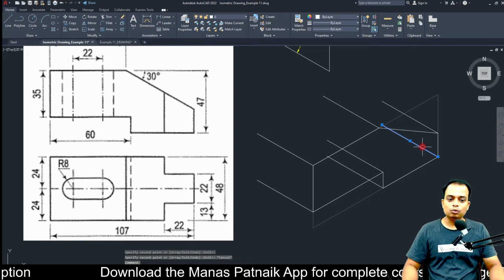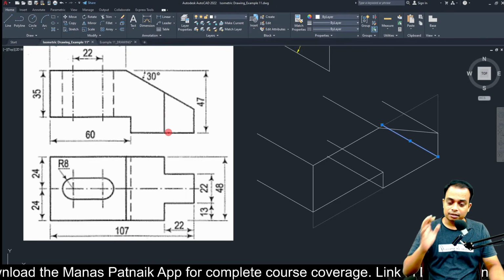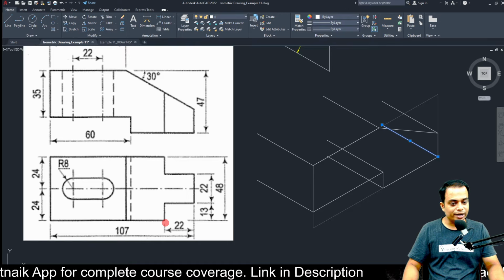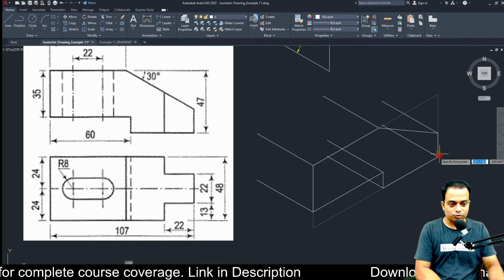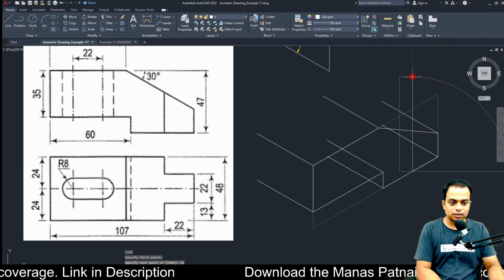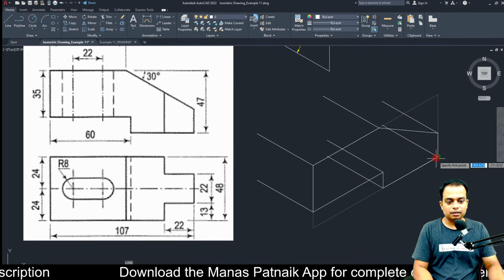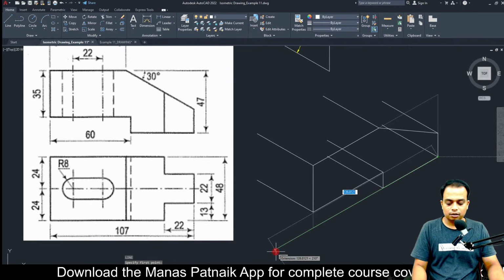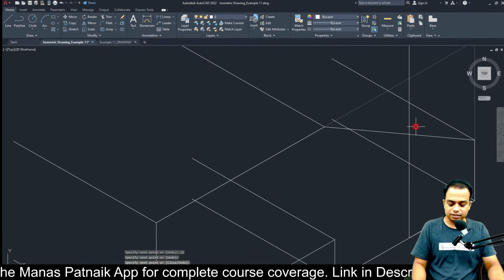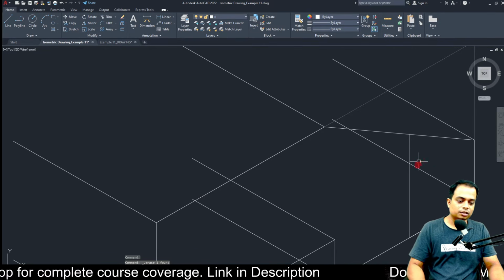I think there is something which is remaining. We are yet to make this portion. How far is this line? Sir, this line is to the left of the rightmost corner by a distance of 22. So what we'll do is, at a distance of 22, come to the left, 22, and then go straight upwards. Here is a line command. L, enter. This way, 22 millimeters, enter, and then straight up, enter. Wherever it intersects, TR, double enter, cut this, chip off this portion. This is what you need.